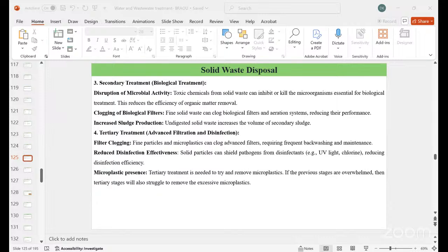Coming to the next one, which is the multiple hearth furnace, where a series of stacked circular hearths are used, and waste moves downward as it is heated and combusted. The applications include roasting ores and reducing metal oxides, producing activated carbon, calcining chemicals and minerals, incinerating sewage sludge and other waste materials, and treating electronic scrap. The temperatures range from 800 to 980 degrees centigrade.